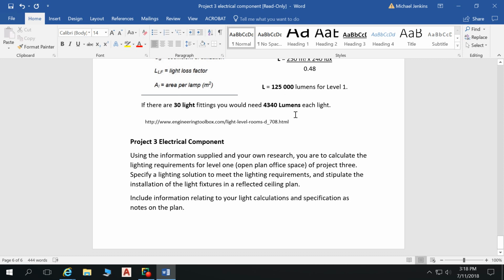In regards to how we think about a reflected ceiling plan, the best way I think to think about it is, like every other plan, we're viewing them from on top. If we draw a floor plan, it's as if we're standing over it and we're looking down on it, and that's our floor plan happening there. We do the same with our ceiling plan as well, except if we were to look at the back side of our ceiling, we'd just see the back side of our lights and all the hangers for the suspended ceiling and so on.